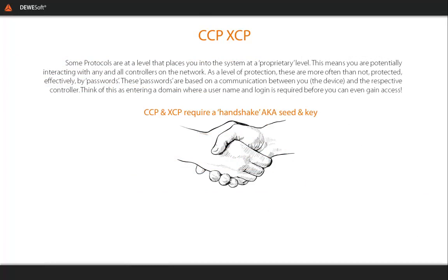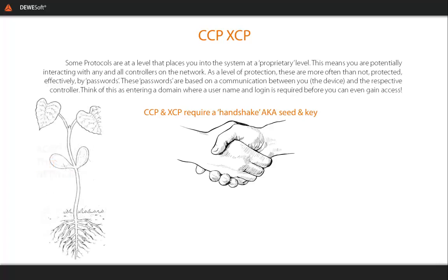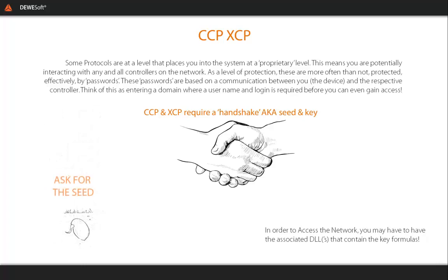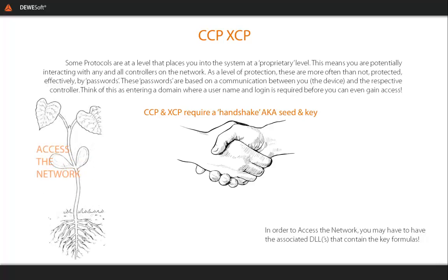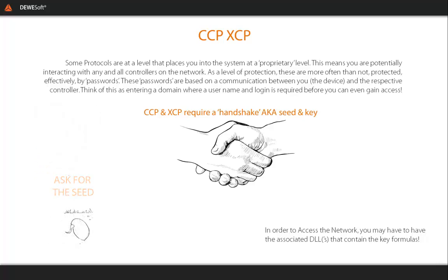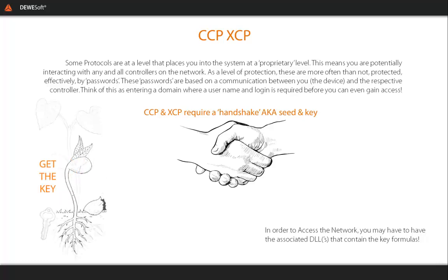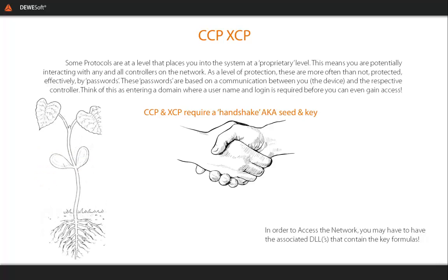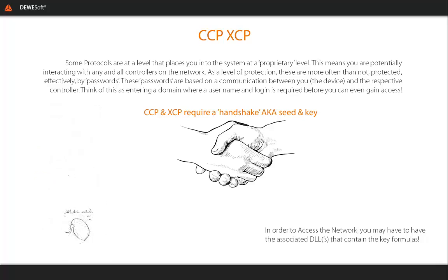The use of CCP is a significant step beyond DBC level CAN. This is because a DBC fundamentally will describe what it is, where it is, possibly with a how to ask for it. But that is about as far as it goes. The CCP and XCP level is where you can get the same stuff as well as tell devices to prepare and send very specific pieces of information, as well as providing the ability to write entire memory blocks, thus affecting that information in the first place. Now, great care should be taken when using these beyond the interrogate level.